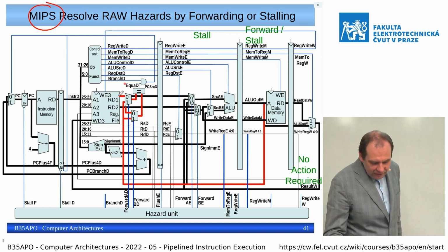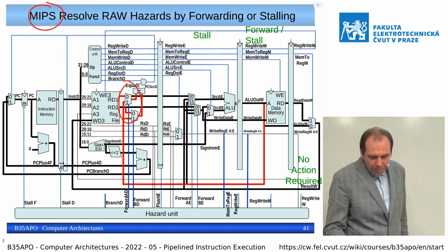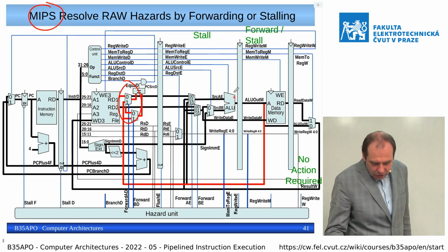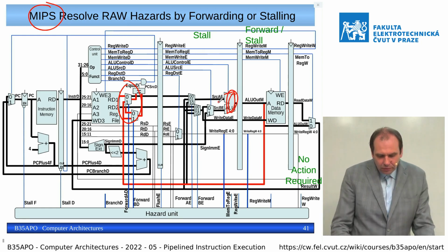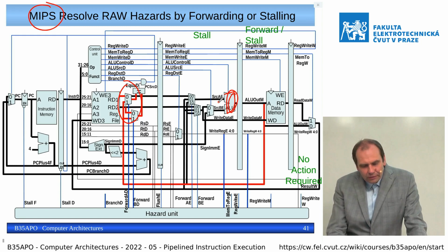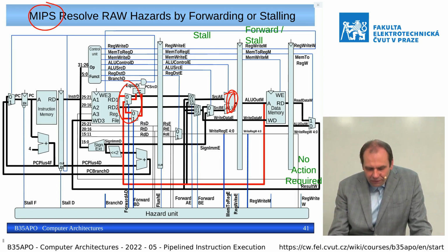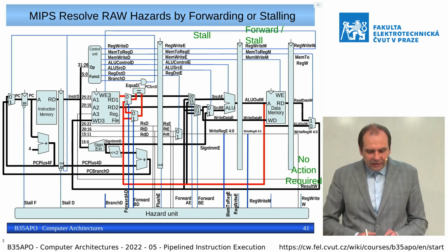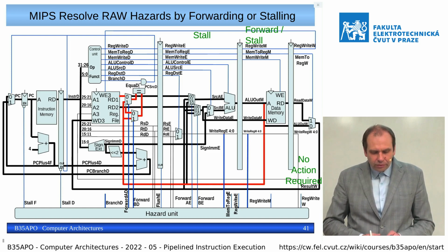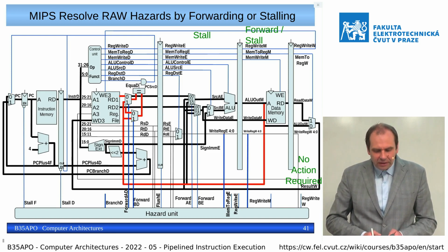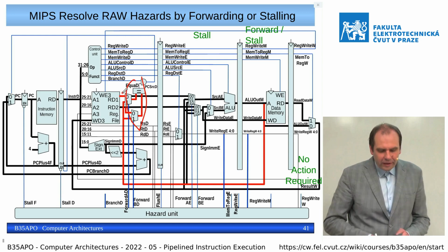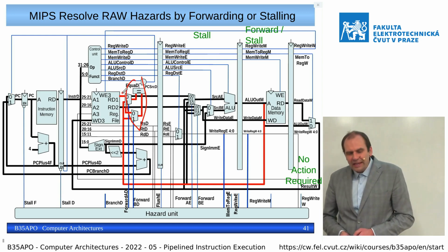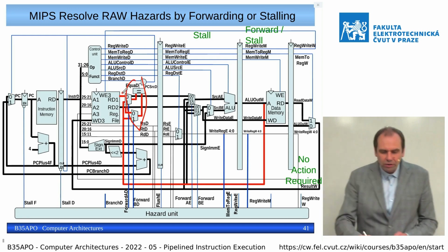In this case, we cannot compare the values where one of the registers should be set by the result of the ALU from the execute stage. So if we do not define in the instruction set architecture that it is not allowed to use the result of an arithmetic logic operation directly for the following branch condition, then again we need to add a stall here.